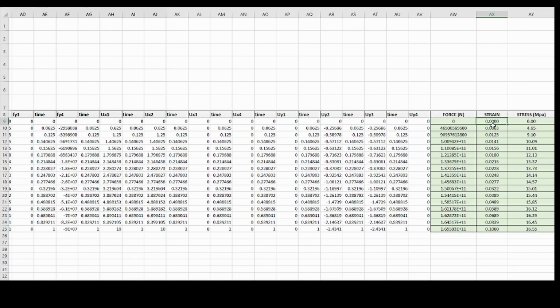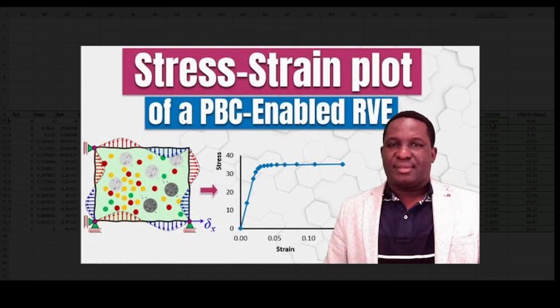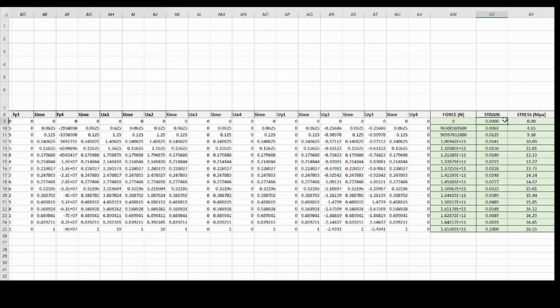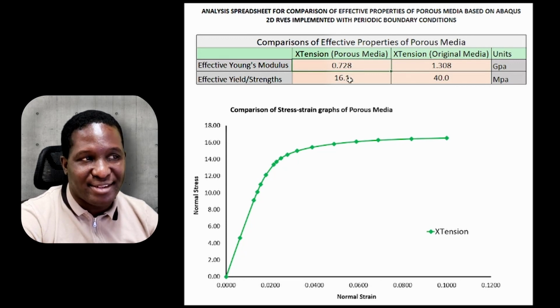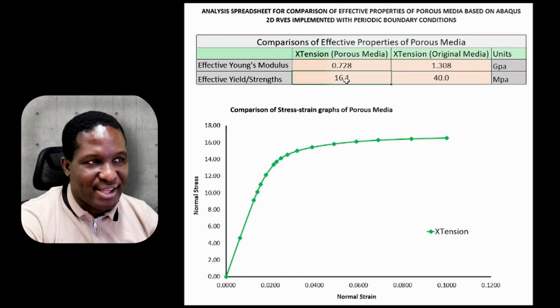If you want to understand exactly what is going on here, I do refer you again to videos that I've made on periodic boundary condition on this channel, and it will explain what is going on here, or you just study this Excel file. The final thing is just a comparison of the information. So based on what we found, the Young's modulus here is extracted for the porous media case, and the strength is also extracted for the porous media case.